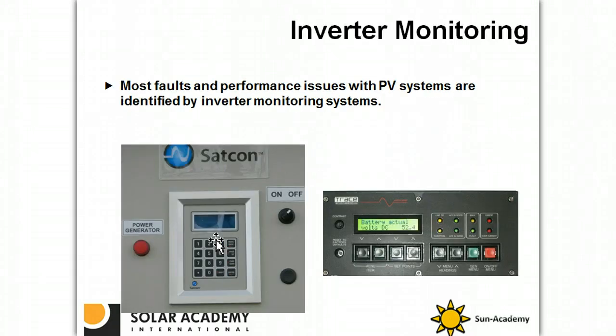Most PV inverters record and display numerous errors, codes, and fault conditions associated with problems in both DC and AC circuits, such as DC ground faults in the array or out-of-range voltages on the array or utility service. Interpreting these codes and messages is a fundamental first step for any troubleshooting activities and helps define specific problems and appropriate courses of action. Extensive details are provided in inverter manufacturer's installation instructions and operator manuals.